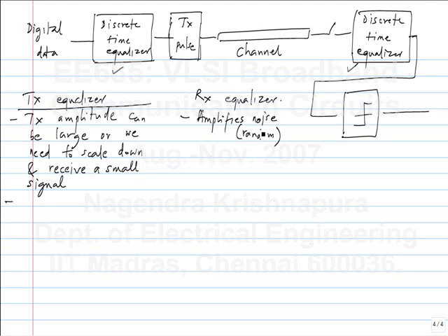Yeah, so we will have to operate within the nonlinearities. That is, we have to always reduce the amplitude so that nonlinearities are not exercised. Let's say we have an unknown, varying channel. What do we have to do? We have to adapt. We have to adjust the taps of the equalizer. So, does it make any difference if the equalizer is in the transmitter or the receiver?